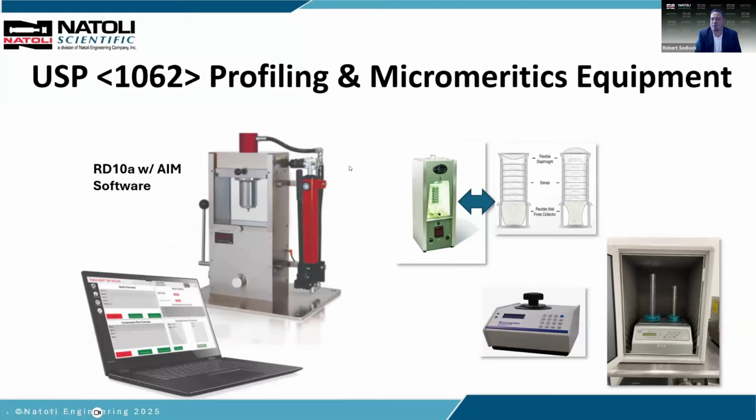Here's some of the basic equipment I'm going to use and show you some of the results. So an RD10A tablet press, very basic single station press, but we're measuring the compression force. The upper compression force or the lower compression force, we're measuring the ejection force, we can measure sticking force, and so on. I also have the sieve stack for measuring particle size distribution.